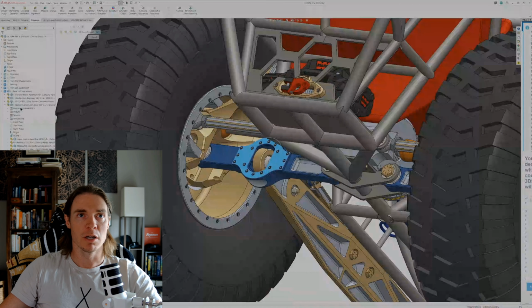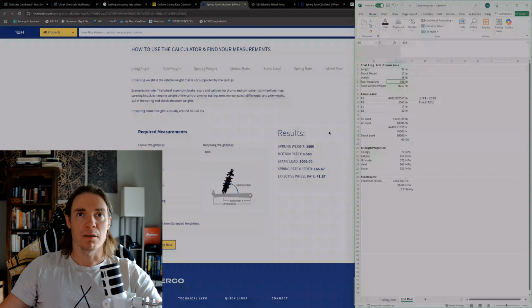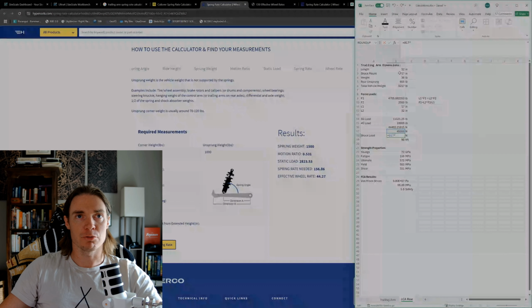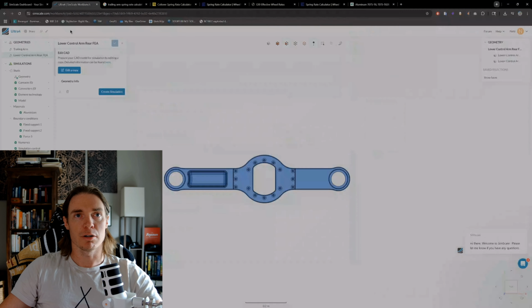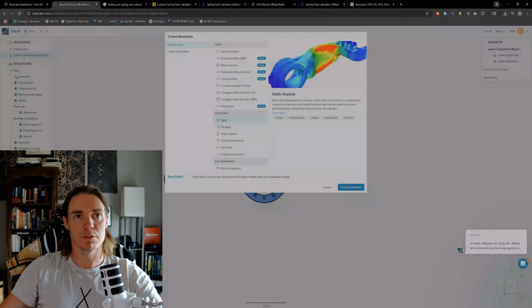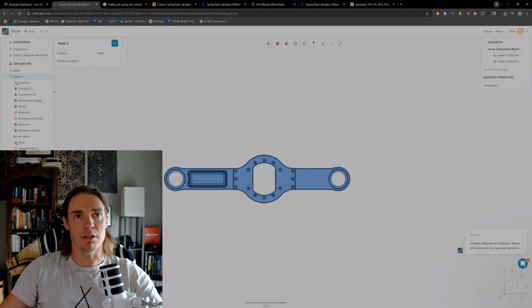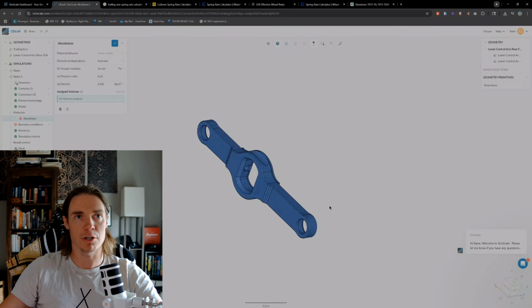So same story, selecting my material, and then I select my boundary conditions, which are 2 fixed supports, and then a force load right in the center on those 2 mounting locations. Negative 90 kilonewtons, so that's the force pointing down, and then this part is ready to run the mesh again.